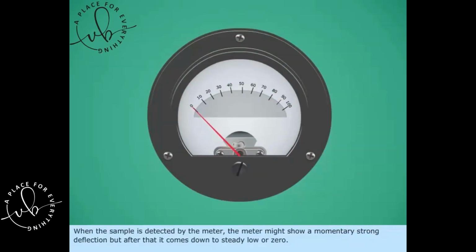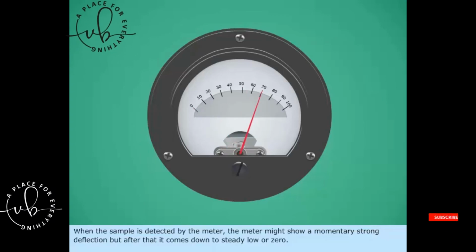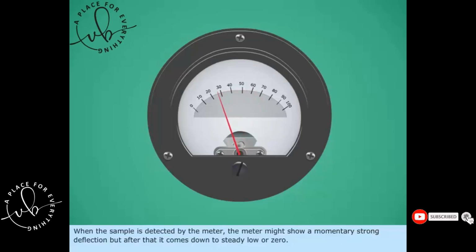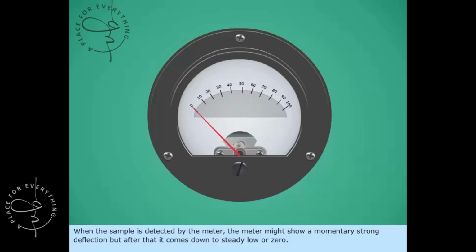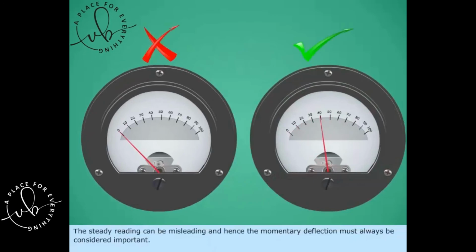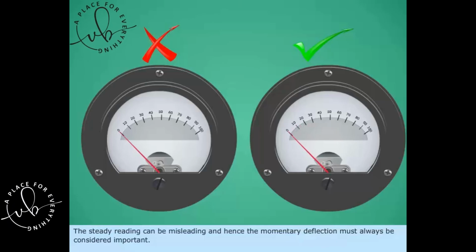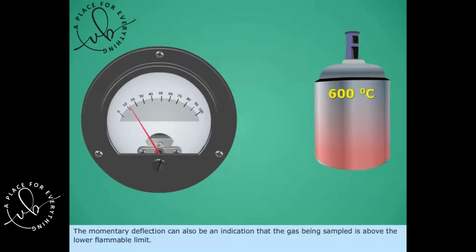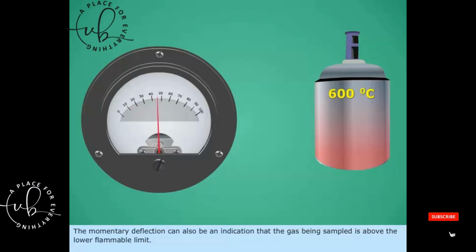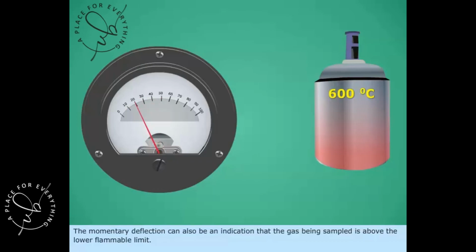When the sample is detected, the meter might show a momentary strong deflection, but after that it comes down to a steady, low or zero reading. The steady reading can be misleading, and hence the momentary deflection must always be considered important. The momentary deflection can also be an indication that the gas being sampled is above the lower flammable limit.